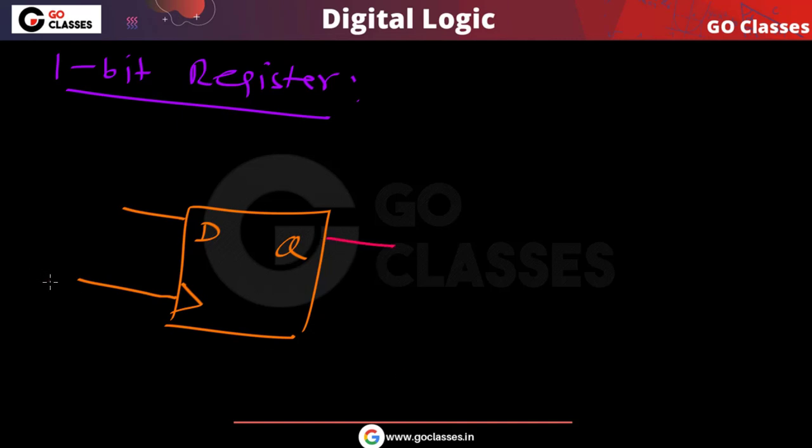Now, as I told you, we need something called a load signal. We want to put some load signal here. We want to control when the data should be stored in this register. This is a 1 bit register, and this is your clock. We cannot control the clock because the clock is the system clock. It is basically a constant pulse.